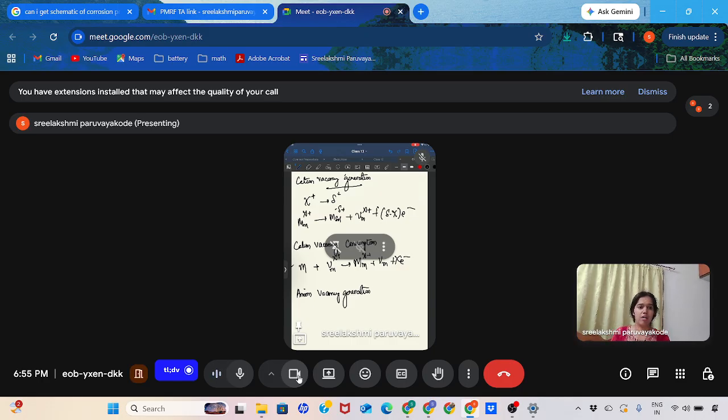I'll repeat once again. You have metal atoms near the metal film interface. They oxidize and form a metal oxide. This is accompanied by the formation of an anion vacancy, and this will cause a continuous thickness increase of the film. This is a non-conserving reaction.